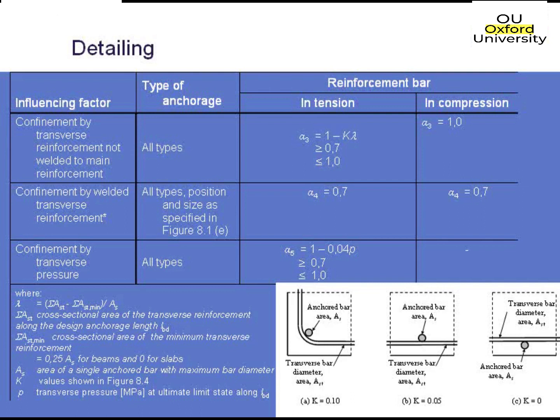So that is what you can do. Generally speaking, I would not recommend that anybody actually uses any of these reduction factors. The reason is that if you've got a typical structure, you do a calculation on all the different anchorage lengths you have. And you probably don't want lots of different anchorage lengths in different parts of the structure, because it's pretty much guaranteed that if you have 3 different types of anchorage lengths for a B20 bar, you'll end up with the contractor picking one and going with that everywhere, and they will mess it up. So it's one of those things.